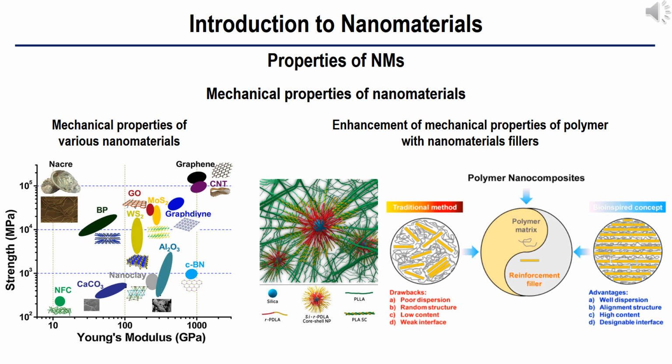In this class of material, polymers filled with silicate platelets exhibit the best mechanical properties and are of the greatest economic relevance. The larger the particles of the filler or agglomerates, the poorer are the properties obtained. Although, potentially, the best composites are those filled with nanofibers or nanotubes, experience teaches that sometimes such composites have the least ductility. On the other hand, by using carbon nanotubes it is possible to produce composite fibers with extremely high strength and strain at rupture.